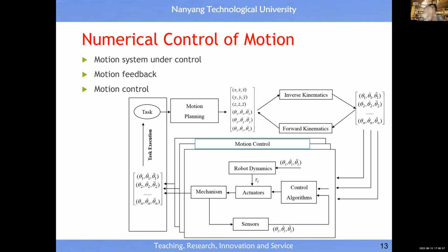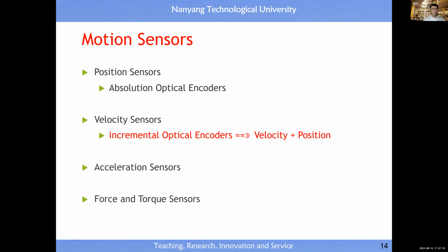But of course, it's relevant to IoT because for internet of sensors, internet of actuators, we may have a digital sensor. Then we need to know how to interface with them, all right? Okay, so for motion related sensors, we have position sensor, velocity sensor, acceleration sensor, all right? The popular one in robotics, in industry, should be the velocity sensor. And the reason is because of its low cost. Another reason is because we can also obtain positional information from this sensor output, right?